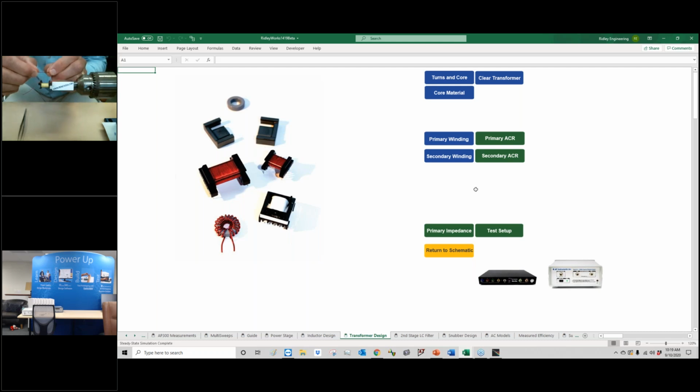So I'm going to go now. Last time I started on the left, and I finished on the right. I like to keep the direction the same, but because there's a flyback, I'm going to wind the secondary the opposite direction. So I'm going to start on the right and end on the left. Now you don't have to do it that way. You can do the flipping on the PCB if you like. But certainly when we're teaching, and just in production in general, I like to be able to just look at the transformer and say, yep, that's a flyback, dots are opposite.